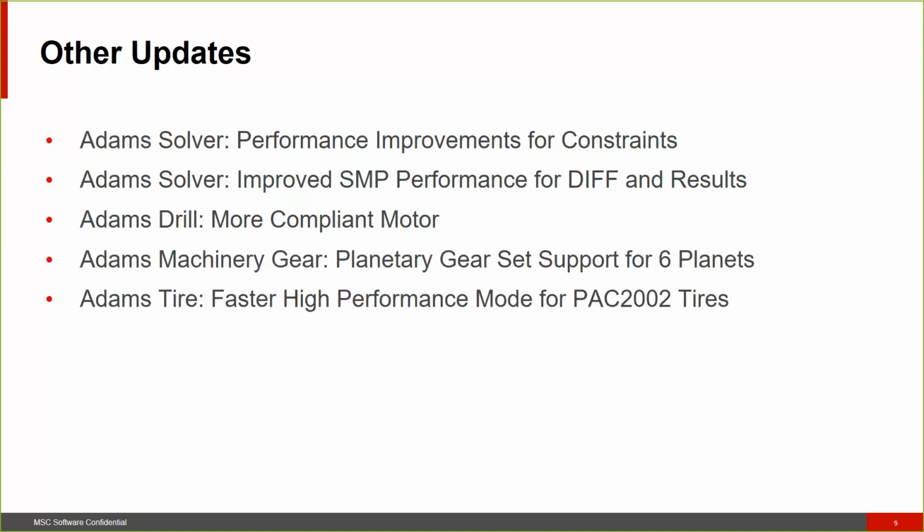The gain here is really due to deactivating the tire general state equations, GSEs as you may know them, during dynamic analyses. This can be done manually through the command language, through the part create or part modify equation general state equation command, which has been extended with a new statics only argument that you can flip on and off.